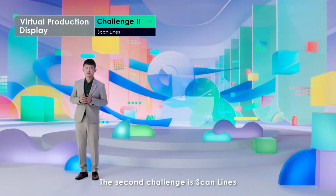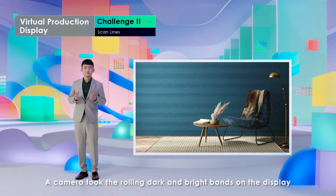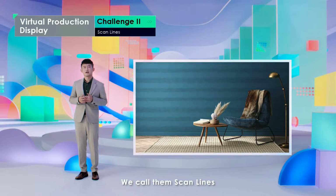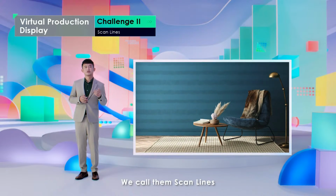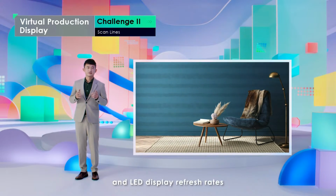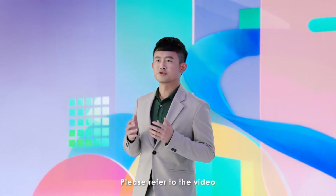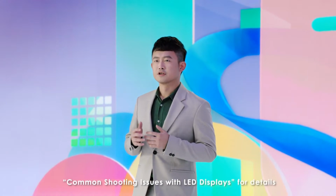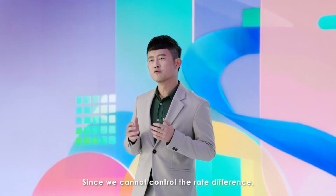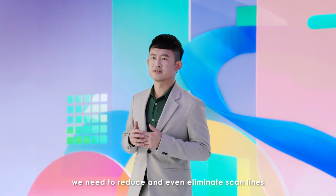The second challenge is scan lines. Let's look at the image. A camera took the rolling dark and bright bands on the display. We call them scan lines. It's mostly caused by the difference in camera CMOS sensor and LED display refresh rates. Please refer to the video Common Shooting Issues with LED Displays for details. Since we cannot control the rate difference, we need to reduce and even eliminate scan lines.